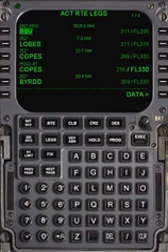The Navigation Database (NDB) is normally updated every 28 days, in order to ensure that its contents are current. Each FMS contains only a subset of the ARINC AIRAC data, relevant to the capabilities of the FMS.